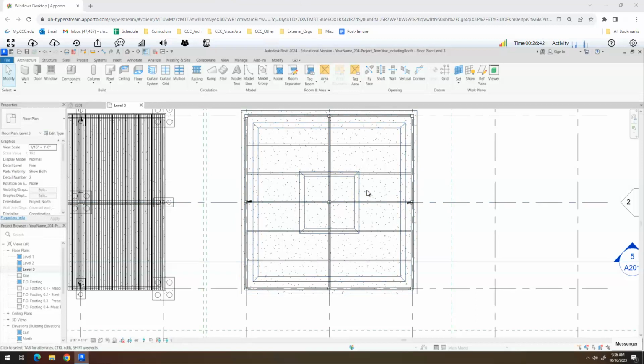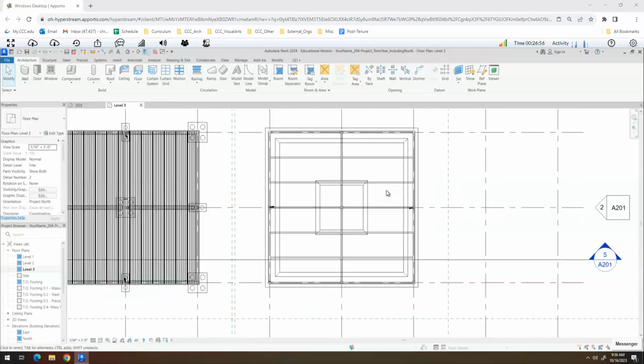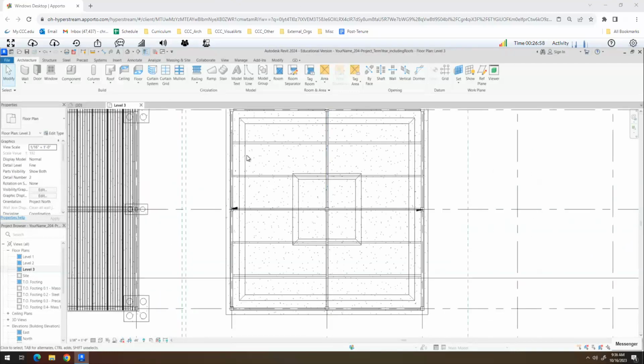Now, the other thing is that when we bring these drains down, we cannot bring them on top of structure. So I couldn't locate a drain, let's say, right here. This would be a better location, and that's where I'm going to put my first drain. So I'm going to take a few measurements. I think it's 8 feet 4 inches from this grid line is where this one is. So a drain that's 4 feet 2 inches above here would place it in the center.